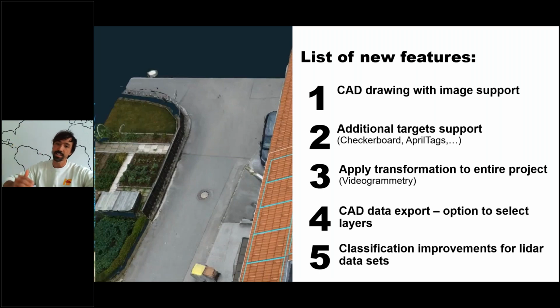If you have a number of layers when you are connecting a survey map and you would like to export just a single layer, now you can do this really quickly. And nevertheless, we know that drone lidars are more and more popular in the drone world. In case you have high forest or something like power line cables, the lidars are super nice things. Also, we improved our classification, which now works really nicely from the point clouds, from the lidar, and you can really nicely extract terrain level in between forest.